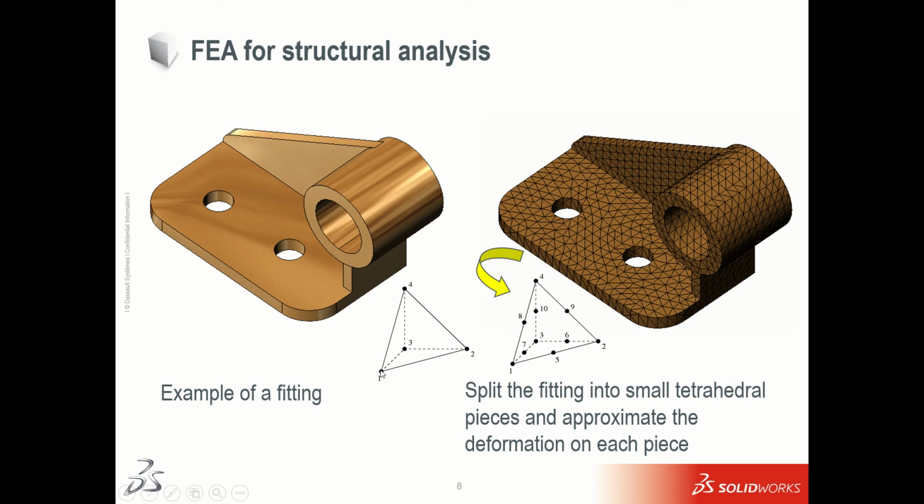The first image indicates a draft quality mesh, which is a first order element. It contains four nodes, and this is a pyramid kind of structure. The second one is high order, high quality or second order, which contains 10 nodes. Means in between two nodes, one node is there. So these 4 plus 6 give you 10 nodes.